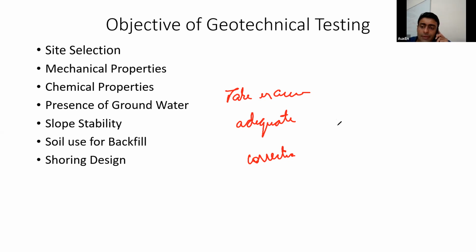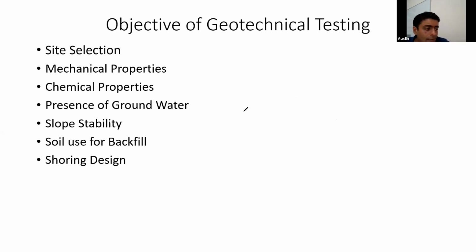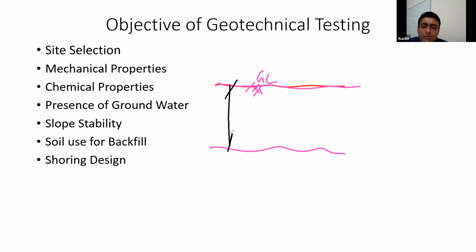Then the second question being asked by Prasad sir, generally what type of measures need to be considered in black cotton soil for shallow foundations? Yes, in shallow foundations, ideally you should remove the black cotton soil. All right. For example, let us say this is your ground level, and let us say you have 2 to 2.5 meters of black cotton soil. So ideally you should remove all the black cotton soil. That is the most ideal situation.